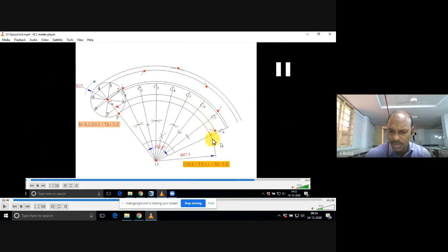Now here you see, this is the curved path. The starting point of the curved path is P, and the end point of the curved path you again call P only. So starting from P, join all these red generated points and end with the last point P with a smooth curve using an HB pencil. That is the required cycloidal curve. Now take your HB pencil.